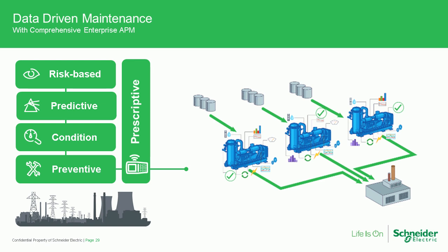And then there's an analytics piece that goes on the back end of that. Once we detect that alert, that anomaly, to really drill in and come up with likely causes and needed actions. And typically that's a longer horizon thing. So it's kind of like, hey, you think within the next 6 months this asset could fail, so you better schedule a shutdown because we believe there's a crack in the shaft of the generator set or something like that.